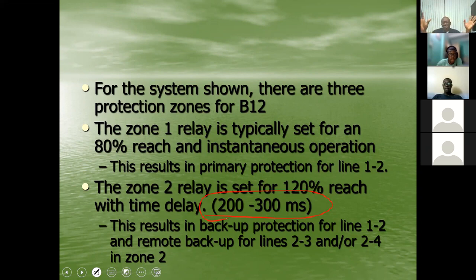But I am oversimplifying, because you also have to consider that there would be a relay at Cane River looking back at Hope so that you have the overlap. So the fact that it's zone 2 doesn't mean that it is on the adjacent line. It just means that it is beyond the 80%. But beyond 80%, you still have 20% on the protected line. All right? And we refer to that as the in zone. But don't worry, we'll come back to it.